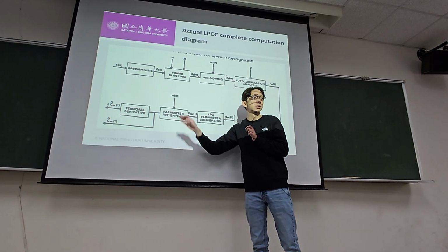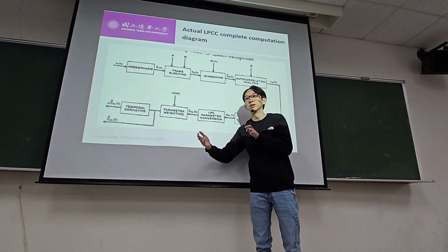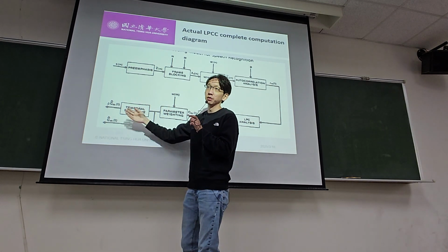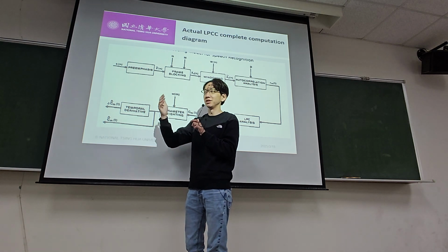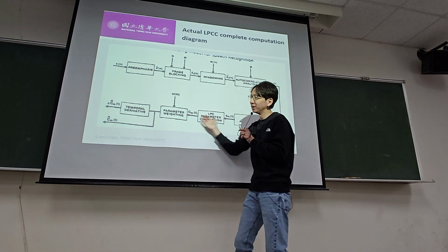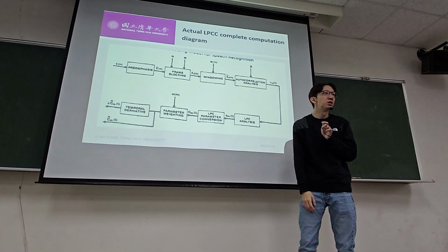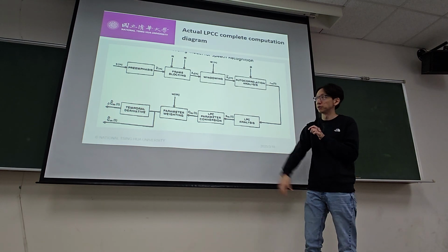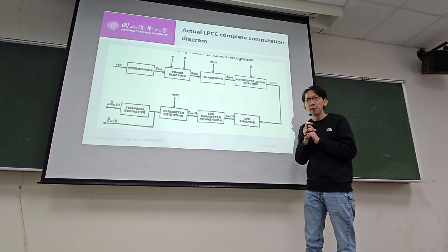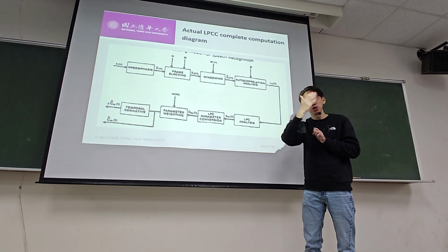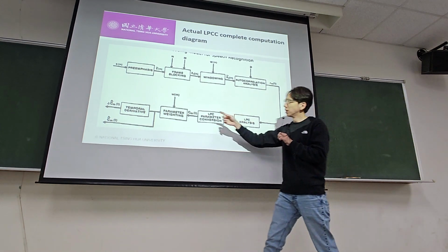It makes this filter become more filter-like, so basically it makes this cepstrum coefficient a little more clean, a cleaner version of it. You clean it once and then clean it again, so it relates more to the filter part of the curve. If you don't do anything here, it'll have the source involved. So that's the whole speech coefficient computation.